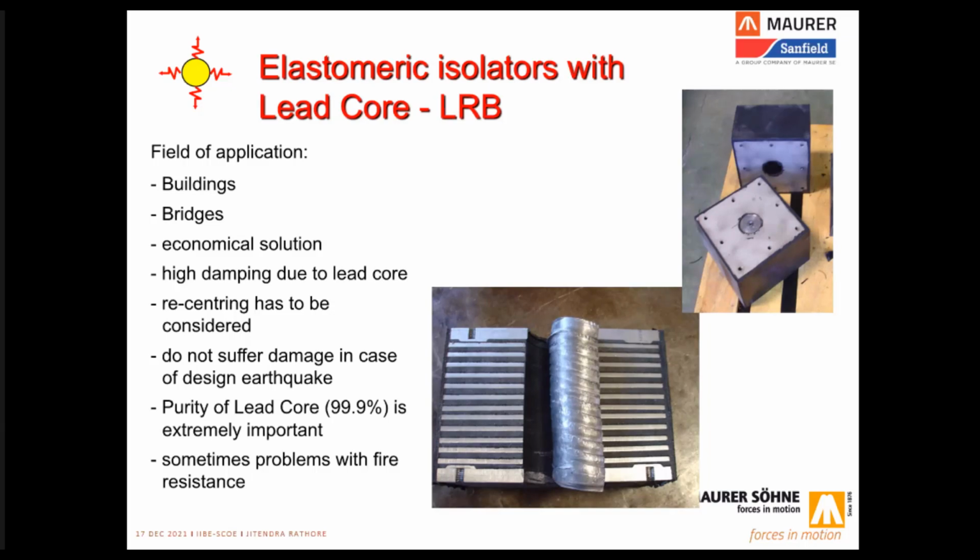So it is something which has certain plasticity. It deforms, but it consumes a lot of force input while doing the deformation. But it doesn't reach the ductile or failure limit. It doesn't break apart, but it keeps on deforming and consuming the force input. That is what we call damping. Damping is basically consuming the force and dissipating it, in terms of heat or some other way, and that's how the earthquake forces are dissipated.